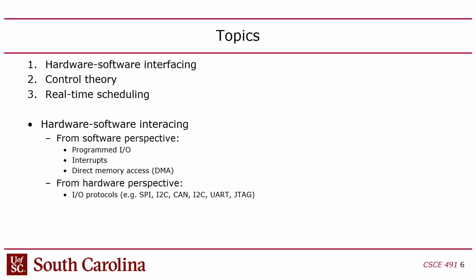You have these things called I/O bases, I/O ranges, which is when you store to a special magic address, and that magic address is usually something that has to be physically baked into the hardware. It's not changeable, it's not programmable. Basically, these addresses are fixed.